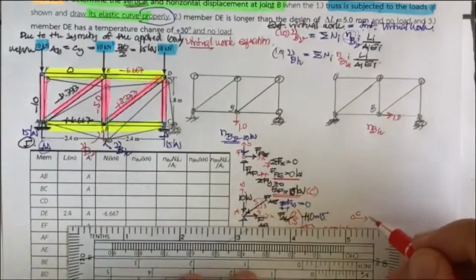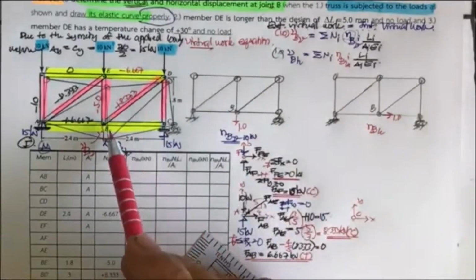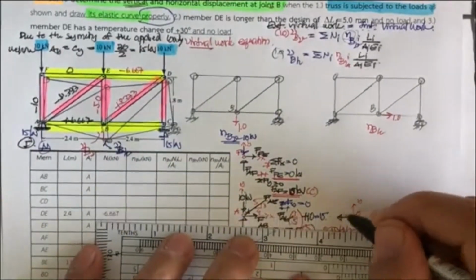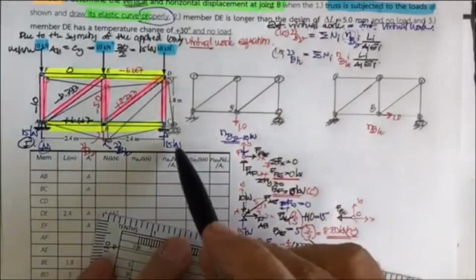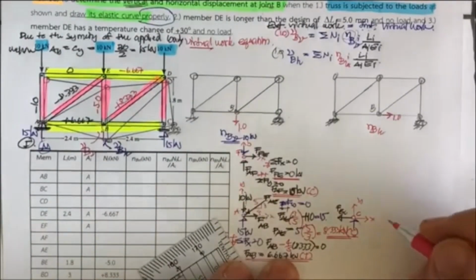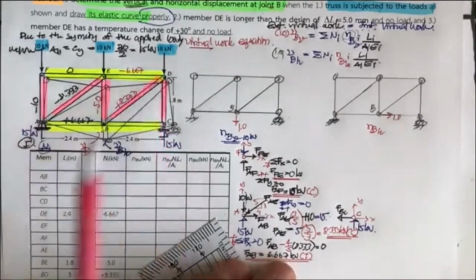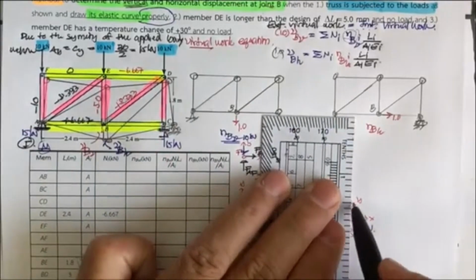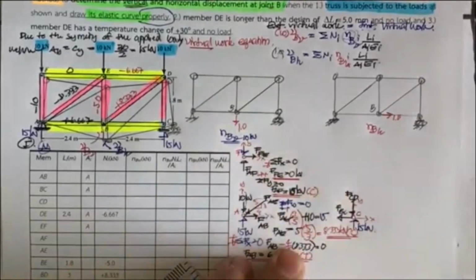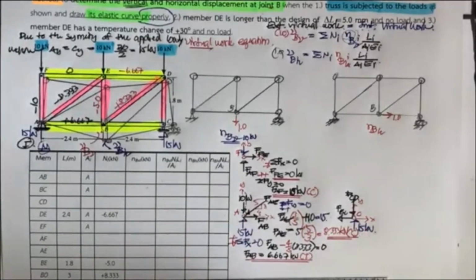This is going to be the X, this is going to be the Y, and we have this member BC. So this is going to be the member F sub BC, and this one has 15 kilonewton acting here. That is the reaction C sub Y, that is 15 kilonewton. What we have is the CD. So the CD for sure is going to be in compression. This is going to be F sub CD. And now you can determine the force easily, right?